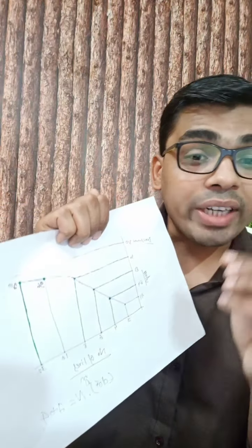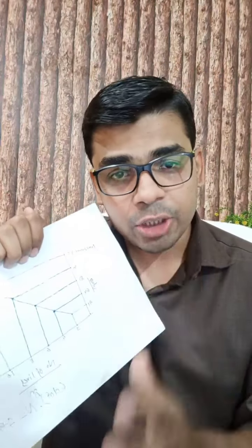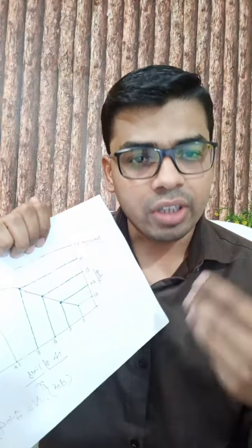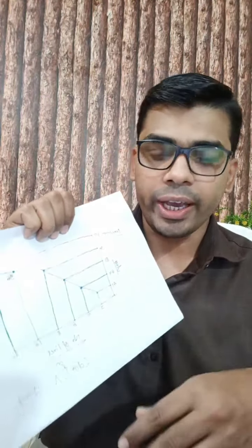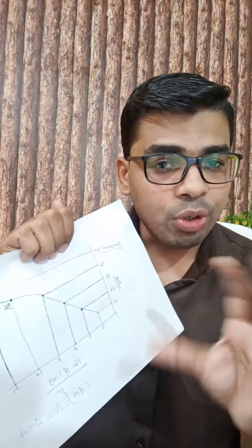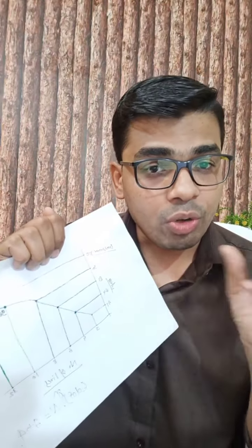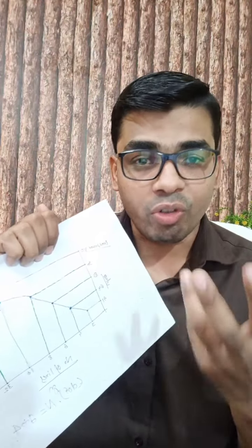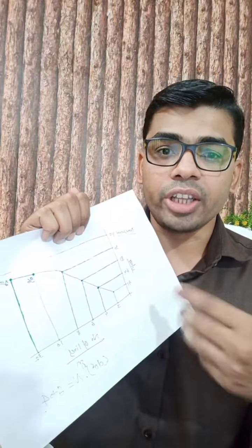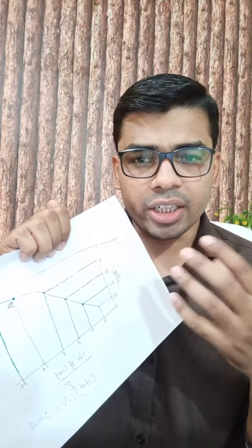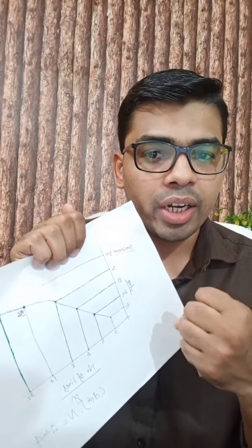Depending on what type of analysis you are solving, whether it's implicit, explicit, linear, non-linear, dynamic, the time will increase and that will vary. And also the size of your mesh, the model size, the computational power and the hardware power of your workstation or the computer on which you are solving. These all are important things, and the graphic cards, memory, lots of factors are involved in getting the results. And again, it all basically comes under the solution time.